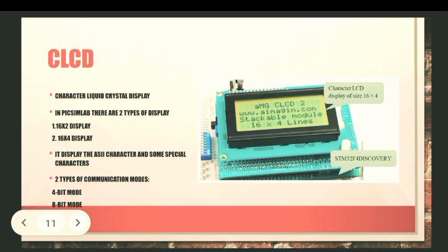Timer is an important application in an embedded system, a default peripheral which maintains the timing of an operation that is synced with the system clock and external devices. It has many applications for measuring time and generating delays. A timer counts the time intervals between events and has a resolution of 8 or 16 bits. It maintains up count and down count, and a quantum which depends on a prescaler ratio such as 1:1 and 1:8.